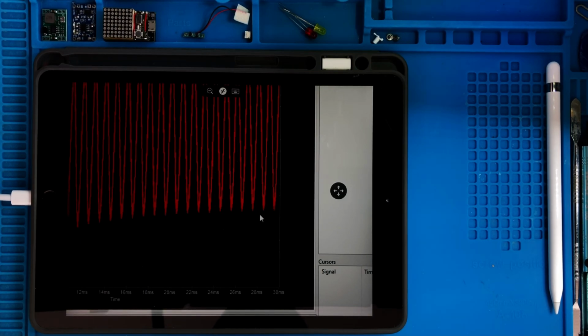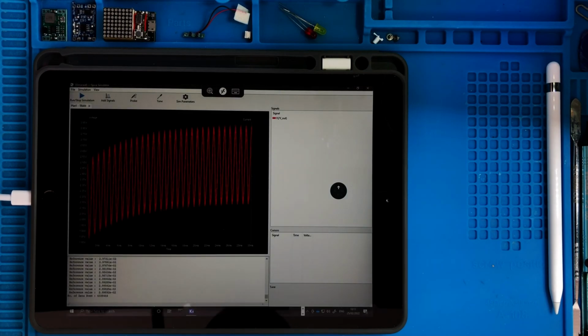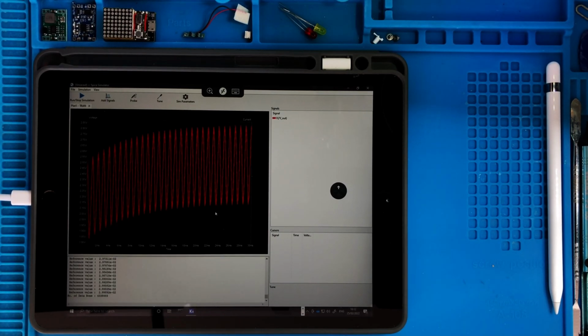If you run the simulation for a longer time, you will see that this value here, this pedestal, stays stable at that level. This is interesting because in this case what you know is that you can't just turn on the circuit and rely on the data from the very beginning, because it takes a while for the circuit to reach a steady state. In this case the steady state is reached after only 20 milliseconds, but this is for this circuit. Maybe you do something else and it's different. So it captures interesting features.